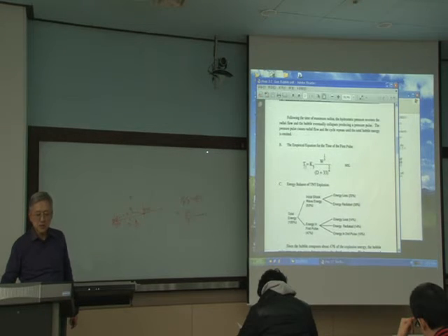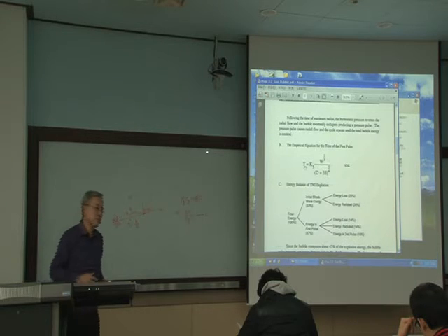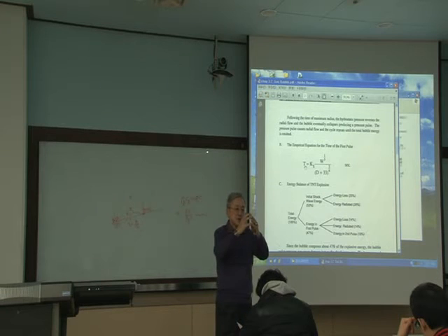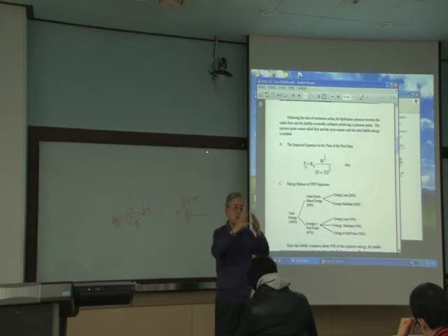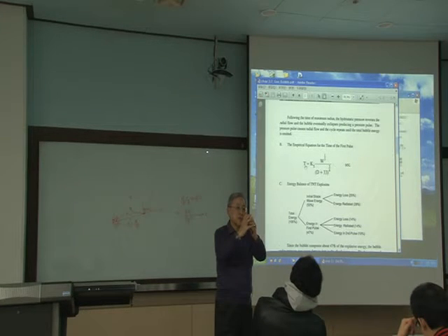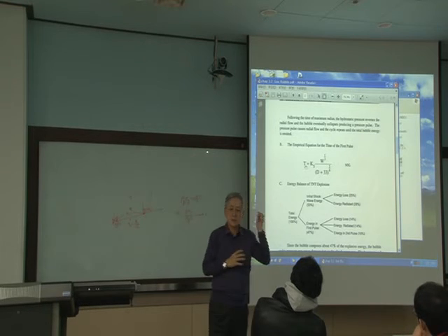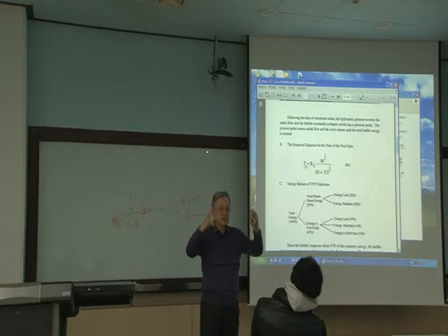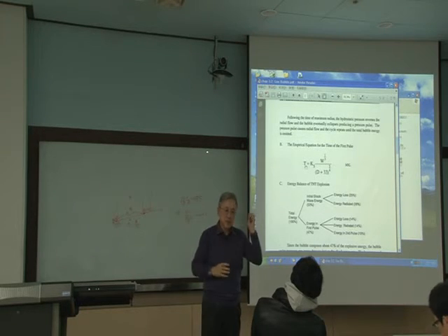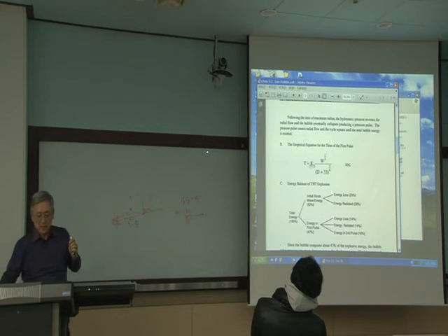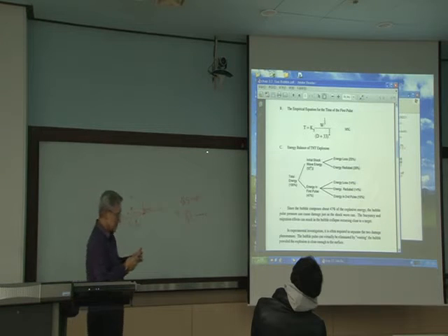And this is the oscillation period. The first period of oscillation, T, is the time that the gas bubble grows to max and down to the min. That's one period. That's what the T is, okay? Not the half period. One period: move to the max, down to the min, that's the time of one period of the gas bubble.